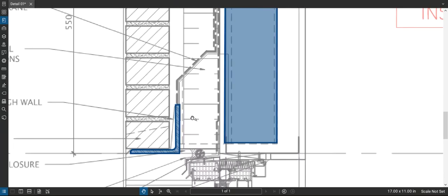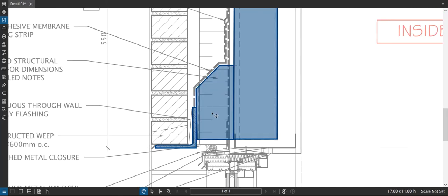And now, this steel angle has to attach to this steel tube coming down here. So what they've drawn here is a knife plate, which is going to be welded, or bolted in some fashion, to this, and then welded to the steel angle, or again bolted in some fashion. So I'll highlight that. There's that knife plate, the way they've drawn it in this detail.